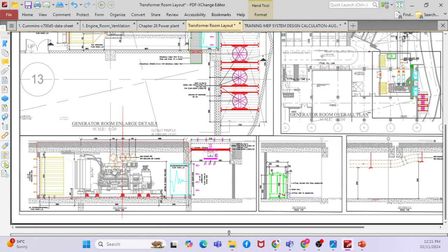In that case, your generator inbuilt fan cannot handle that pressure, that much air, right? If you provide this much attenuation and these accessories, the generator fan will perform with less efficiency. Then the heat of the generator will go up, and the generator cannot perform properly. That is why you provide an additional exhaust fan to push the air from outside to inside, so that the generator fan has less work. Clear, right, everyone? Yes. Okay, so that is why we provide the additional fan.